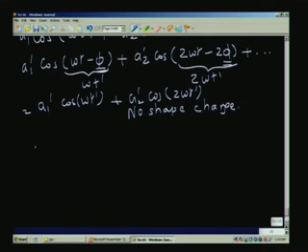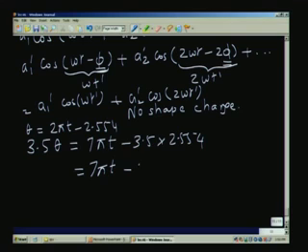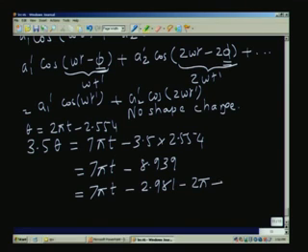So, let us look at that. Suppose I take 3.5 theta, where theta is equal to omega t minus phi, that means 2 pi t minus 2.554. Instead of that, omega t prime equal to 3.5 theta is what I am writing, because this will become 3.5 times omega t prime. So, 3.5 theta will be nothing but 7 pi t for the next component, minus 3.5 into 2.554. That value is 7 pi t minus 8.939. So, I can write it as 7 pi t minus 2.981 minus 2 pi plus 0.3252.